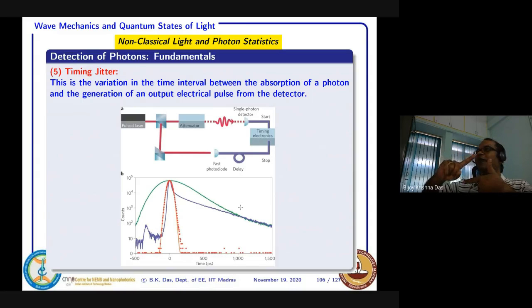So this timing, from the incoming photon to electron hole pair generation, and then that electron, again it will undergo an avalanche process. That pulse will be generated. Once the pulse is generated and measured in the output load, then your count is complete. So this entire process does not take the same time every time, because there are internal mechanisms, internal physics, some defects.